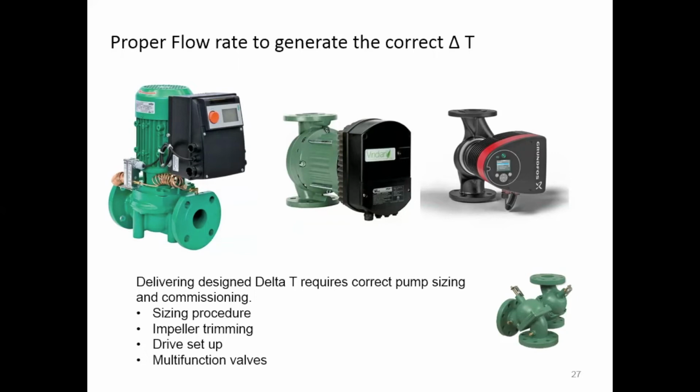But then also, once I size it, the impeller has to be trimmed, if the impeller is going to be trimmed. And what we're seeing now is a lot of pumps that have the VFDs that are integral to the pump, or an ECM motor. A lot of times the impeller trimming doesn't happen, and it's going to be done electronically to limit the upper end of the flow rate of that pump itself.